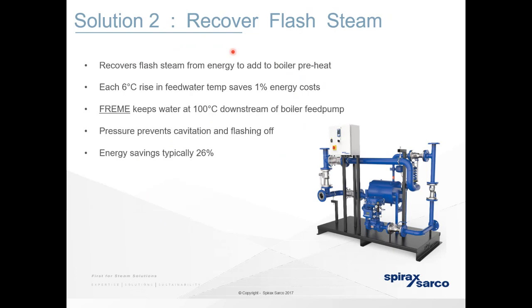You could also use the steam you have. You still have temperature there for washdown units. It's as simple as connecting to the venting pipe on your CRU. You need to be careful you don't pressurize the vessel itself when you're connecting things to the pipes.